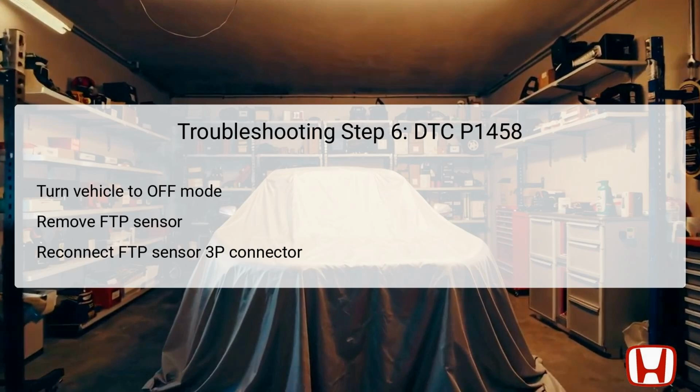If the current conditions do align with these prescribed thresholds, it indicates that the sensor is likely functioning correctly, enabling the technician to progress to the next checks. If the readings do not match the thresholds, this can indicate a blockage within the FTP sensor vent hose, requiring further attention to either clear the obstruction or replace the hose if it is damaged.